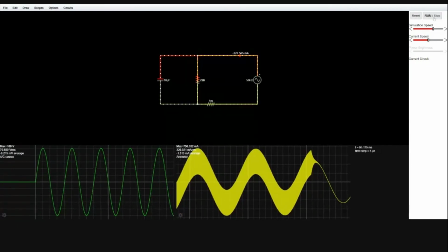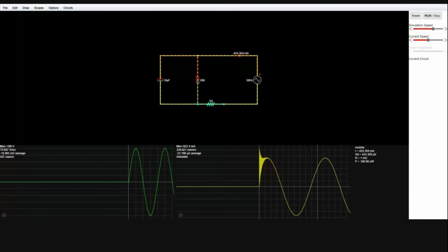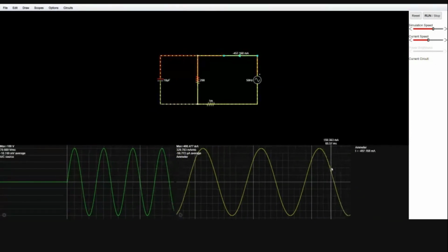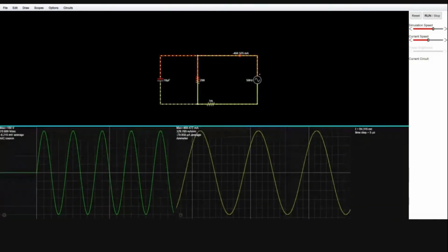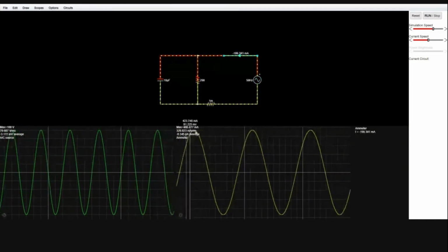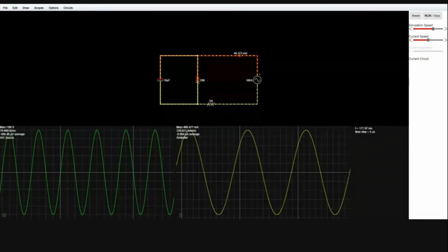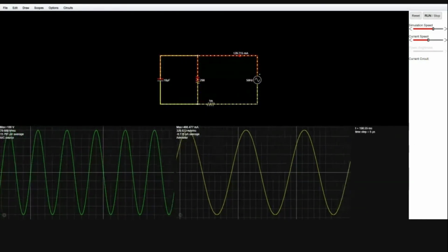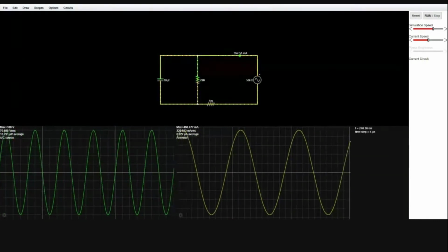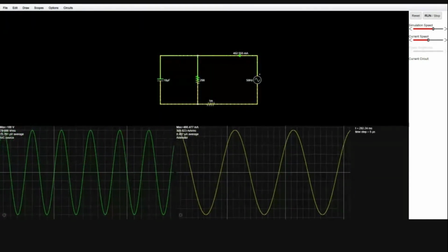Reset. Okay, don't use 1 micro ohm. Okay, use 1 milliohm only. Now this is the current value, right? And I can see what the peak value is and also the RMS value. The RMS value, which is in milliampere, is what is going to be my mod I test. Okay. And the ratio of this is what is supposed to give me mod ZTH. That should match the theoretical value of mod ZTH that you calculate.